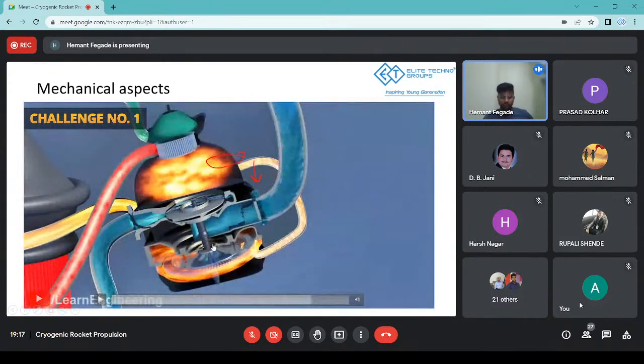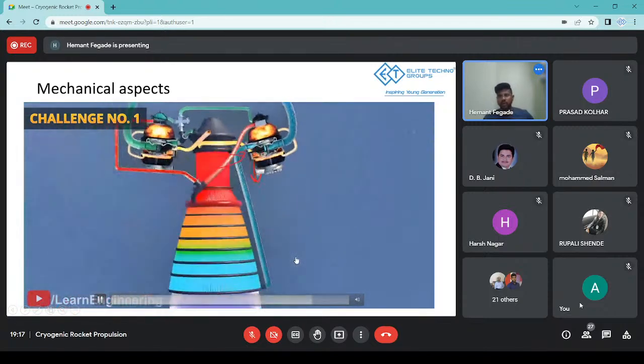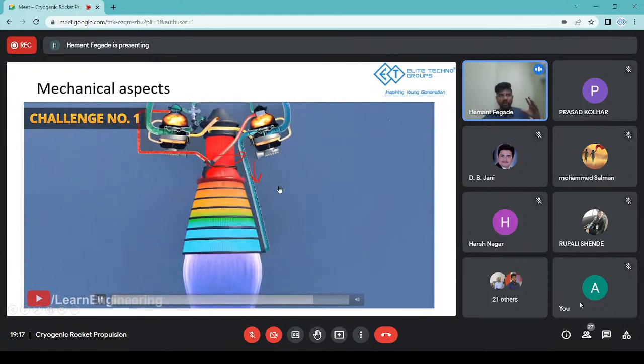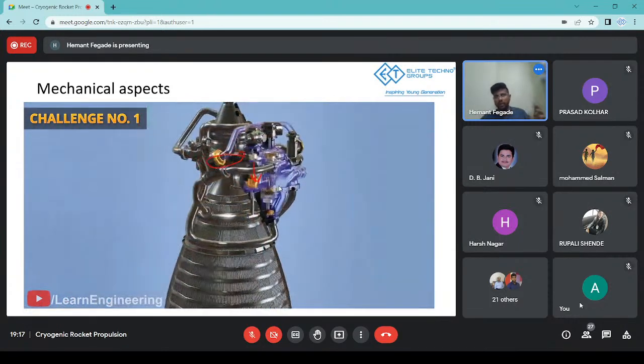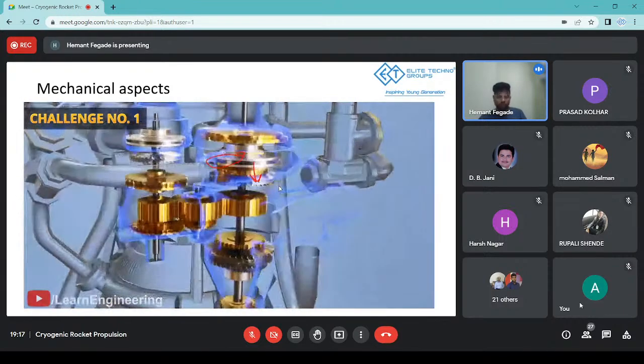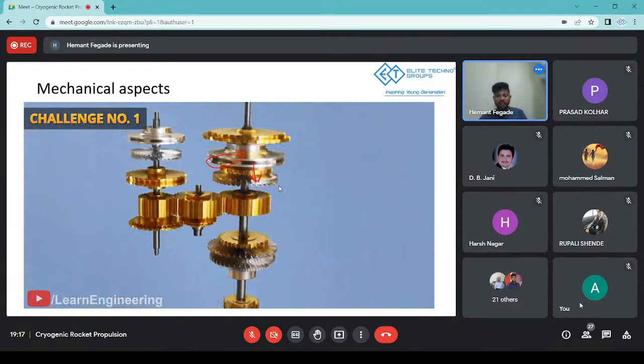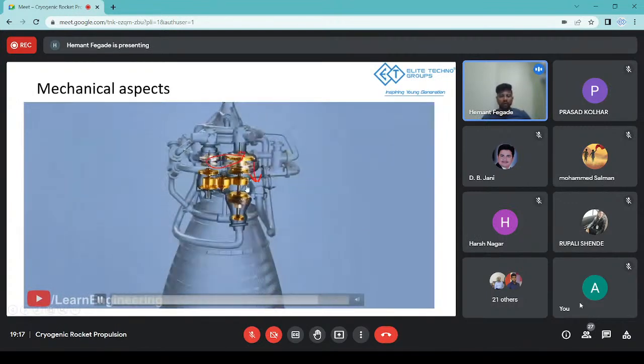Here you are seeing that your impeller is rotating at the same speed as this turbine. So at any given moment, if your fuel enriched mixture reduces its speed, your pumping speed also is affected. To avoid such challenges, people use auxiliary methods like a gearbox to pump the fuel properly and keep both speeds separate, so that even if your turbine loses speed, your pump will not lose speed, and it will become self-sufficient in order for you to run.